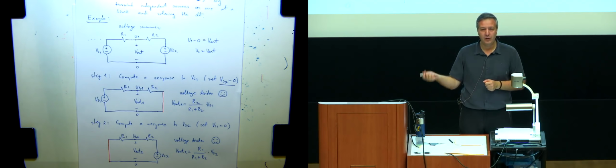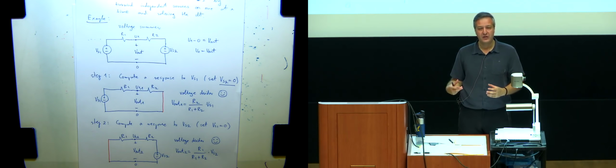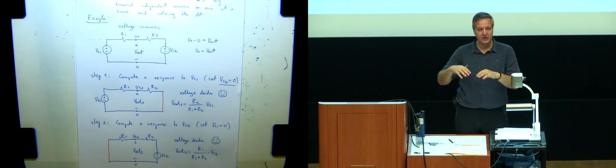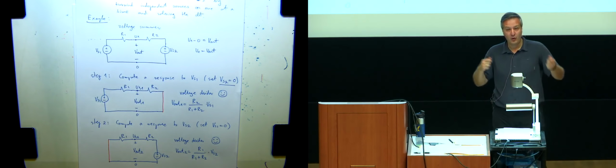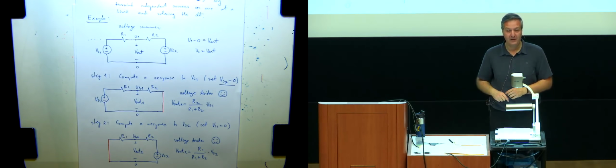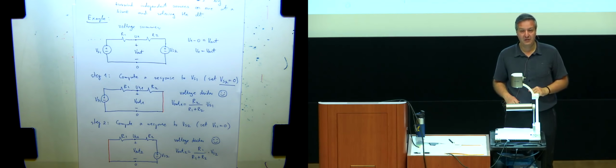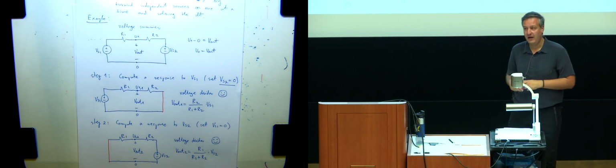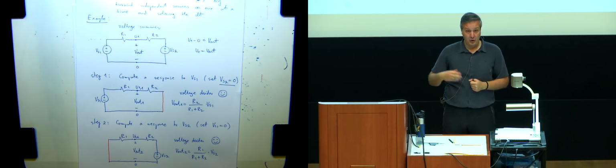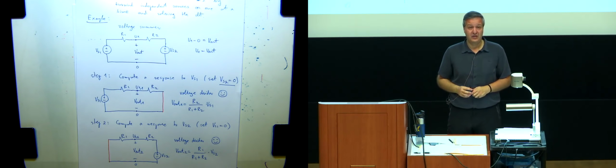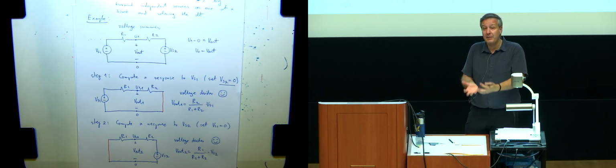In fact, in how we're going to do the touch lab, you are going to build first only a part of it, because you don't yet know how to build a current source. So you're going to build just a sensor and then simulate a current source. And then when I show you the op-amps, you'll be able to build a current source out of the voltage source. Otherwise, just building a current source itself, something that constantly pushes electrons, charge, regardless of the voltage, through some chemical or physical reaction, is actually super difficult.